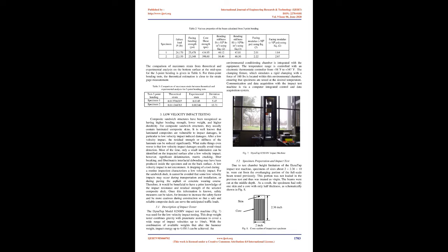strains of the beams. 2.2 Description of testing procedure. The test specimen is placed above the bottom fixture seated on the load cell of the Forney machine. The bottom fixture supports the specimen at the two ends of the specimen and load is applied at a constant rate at the 2 points on the bottom surface. For 3-point bending, Fig. 3, the top fixture supports the beam at the midspan. As the load is increased, deflection at the center increases. Deflection is measured by means of a linear variable differential transformer, LVDT, located above the midpoint of the specimen.